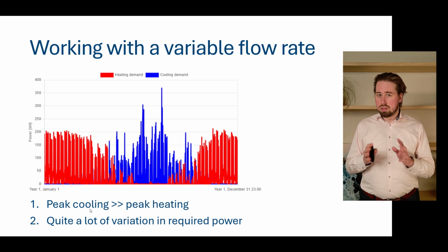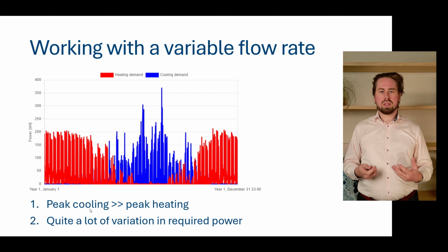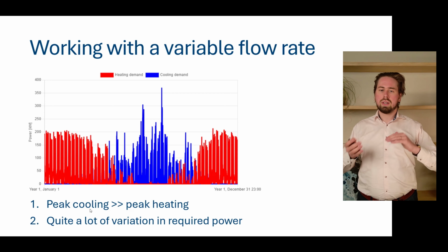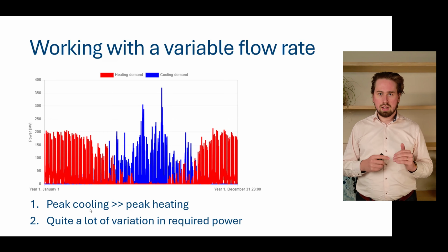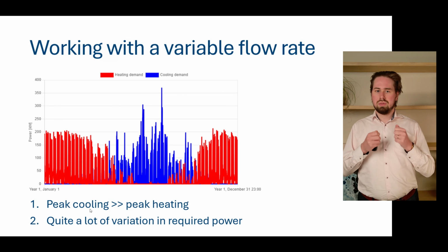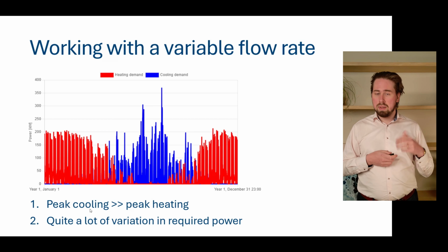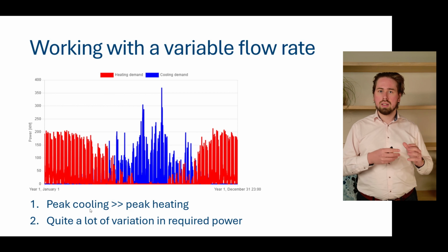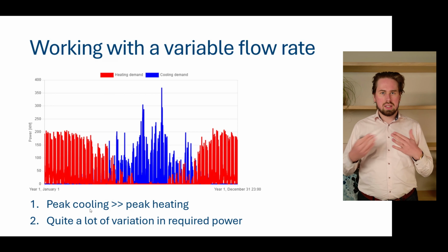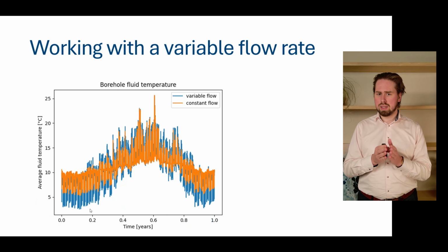And what we did, just to illustrate, is we took this profile, we simulated a borefield with it using both a constant flow rate and a variable flow rate. And we made it such that our constant flow rate was actually set to the maximum flow rate we will have during this peak of 370 kilowatts in cooling to basically match our design. And so our maximum flow rate is the same in both simulations. And the result is given here.